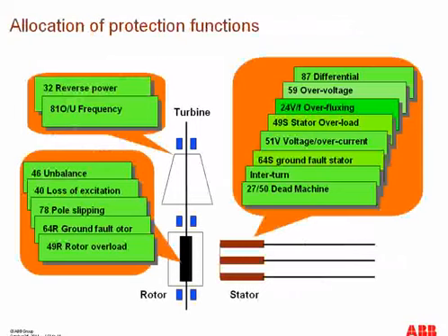And on the stator side, we can put differential protection, over voltage protection, over fluxing protection, stator overload protection, voltage controlled overcurrent protection, stator ground fault protection, interturn protection, and inadvertent energization of the machine protection. So these different protections can be provided in typical protection schemes to protect the parts of the generating system.